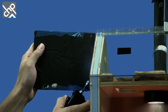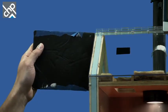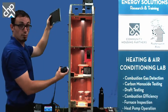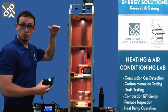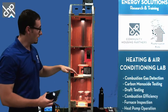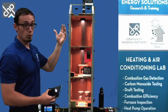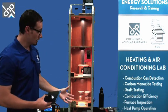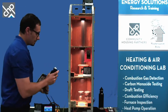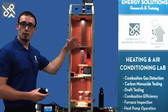So the air in the attic is being forcefully expelled now. So it's moving up through the building, and a big part of it is how tall your building is. That's going to be a driver for stack effect. It's the distance from your neutral pressure plane, and the taller the building you have, the more powerful that stack effect is going to be. So with our little 3-story building here, we've got a lot of stack effect going on. And as I mentioned, that air has the tendency to rise up and out of the structure.